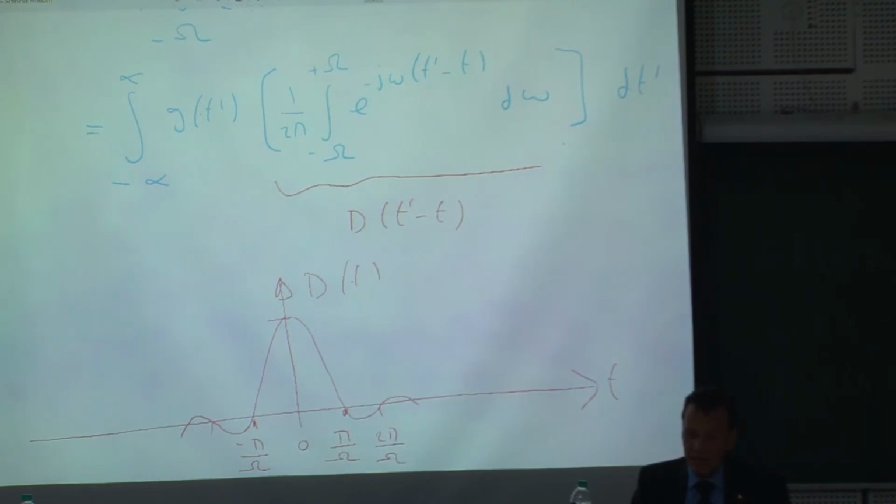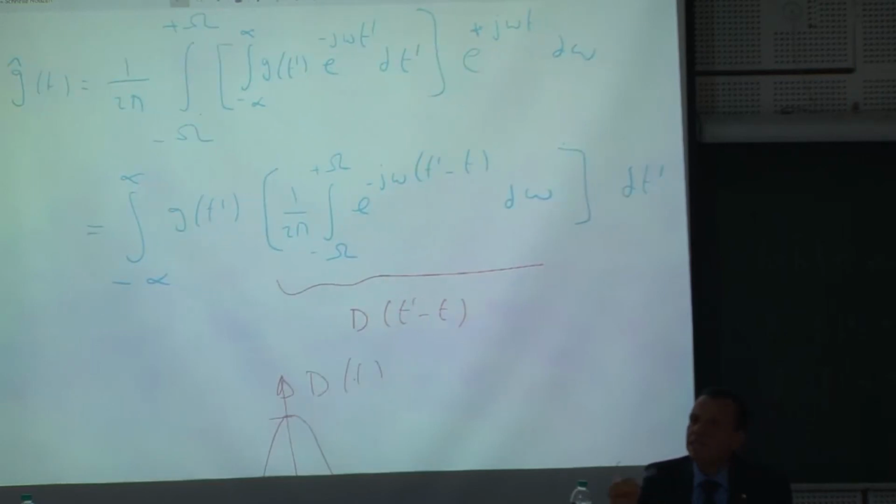So, and you can recognize now that we are convolving, because what is the form which you know, which looks like f of x dash g of x minus x dash, or x dash minus x dx dash. This is a convolution. So this is as a conclusion what we get from limited frequency measurements is the convolution between this function here, this sinc function, and the original image.